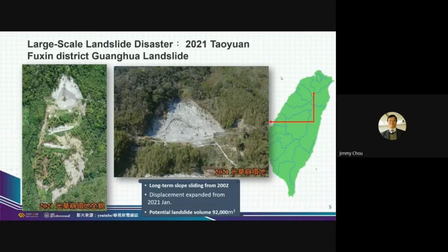So among those 280, the government is trying very hard to design a good threshold for those 280 potential high-risk large-scale landslides. We say large-scale landslide because in Taiwan, the government has decided to define a large-scale landslide as one where the entire landslide area is higher than 10 hectares, or the landslide depth is over 10 meters, or there are over 100,000 cubic meters of material, like the soil and the gravel.